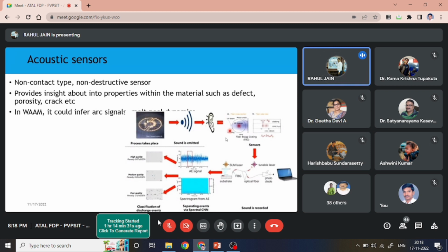So what they do, they measure the sound. The sound is measured through sensors, the FBG sensor, as the name suggests, is one of the sound sensors. It is connected through optical fiber, right, and eventually connected to a computer. Once you get this acoustic signal AE, you need to filter it, remove the noise and all, and then we need to get the features as per requirement.